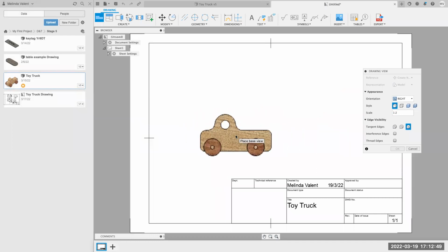If you have a very large object, you might go to 1:10 or 1:5. Use a scale that's common. Don't use a strange scale like 1:3.5. Orthogonal really is important that you choose a standard scale like 1:1, 1:2, 1:5, 1:10, 1:20, and so on up. Okay. If you're not sure, just ask your teacher.